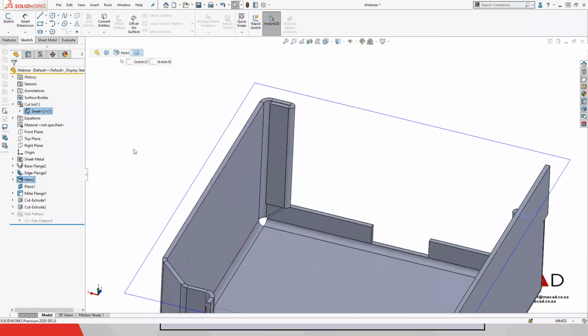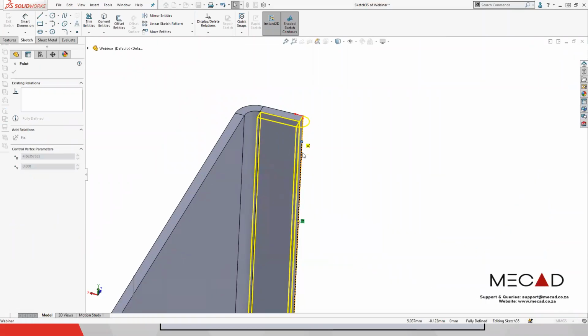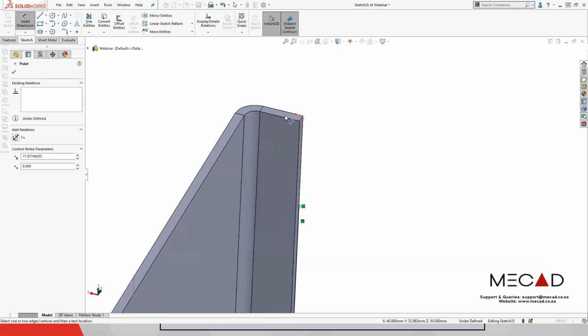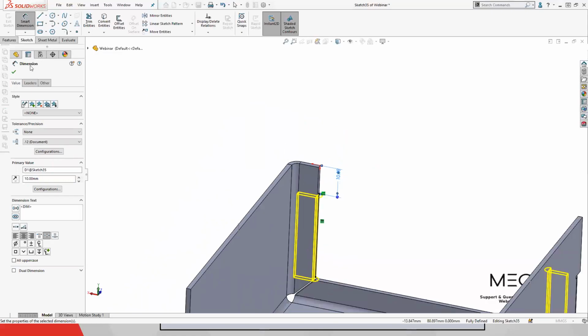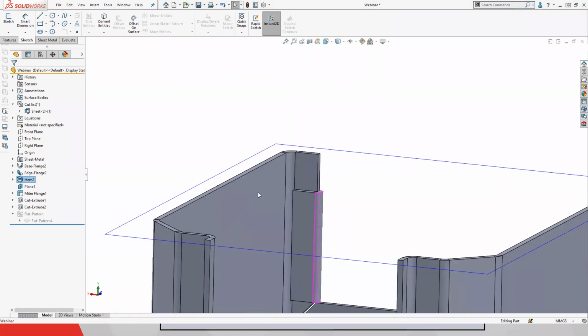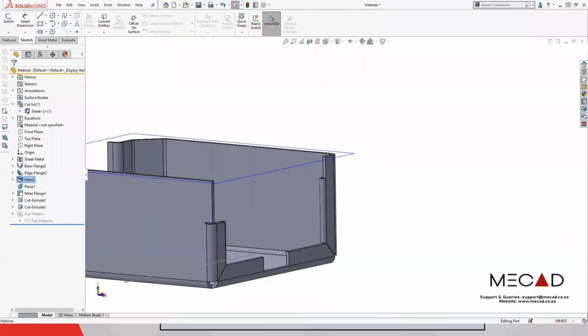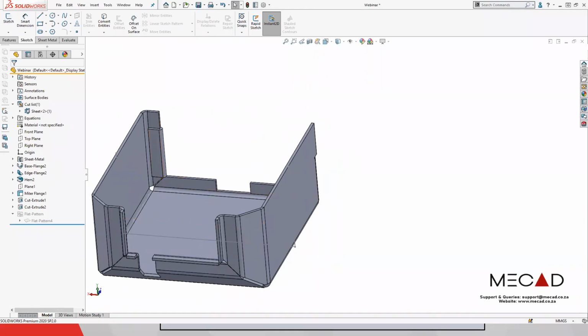Well, the same way we just did the edge flange. By selecting the hem feature, right-clicking and saying edit, we can then just make sure that we're selecting our correct edge. So for this example, edge 2, and you'll notice it just gives me a little line. From there, we know from our consultant that we need a 10 mm clearance. Okay, sorry, my option keeps on popping up on that screen. So we can just say finish, and you will see that your hem updates. Perfect. So I'm going to quickly jump us back to our PowerPoint.